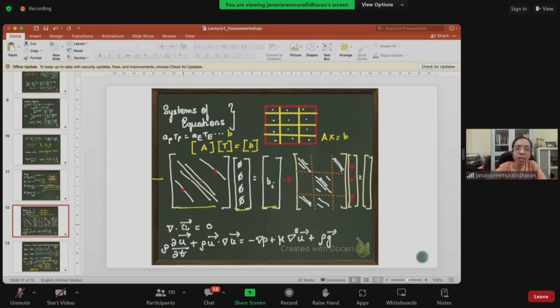So what are you basically trying to do in a flow-only problem, not energy, not temperature? You're trying to iteratively solve, based on an initial condition of U. You get an intermediate U value, which you plug in to get a pressure value. Now, this might not be correct in the first round. So iteratively, you will go until the U and the pressure satisfy both these equations for the next time step. This is how you do the SIMPLE algorithm.